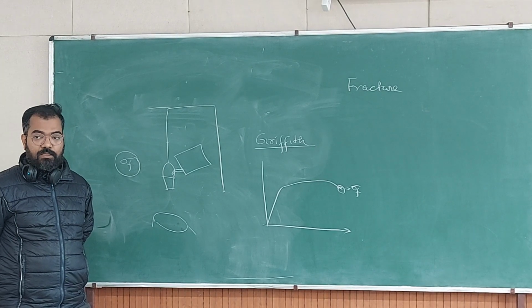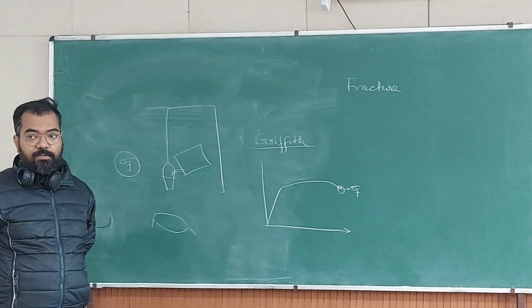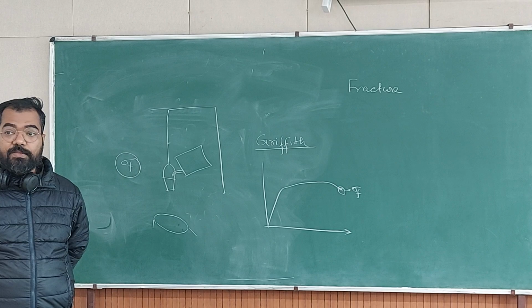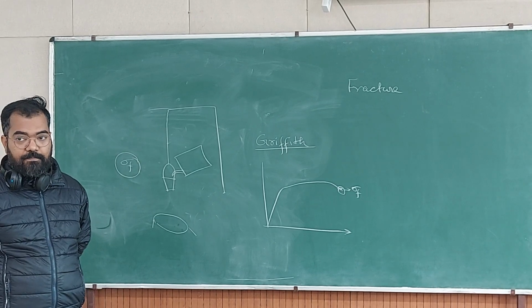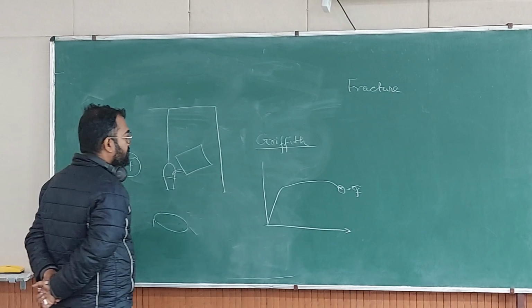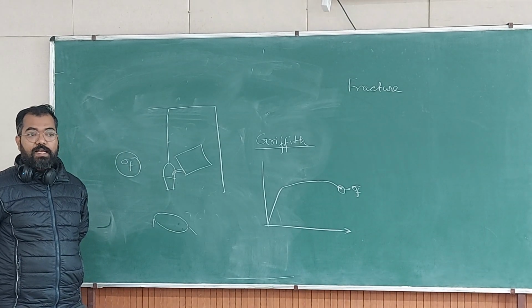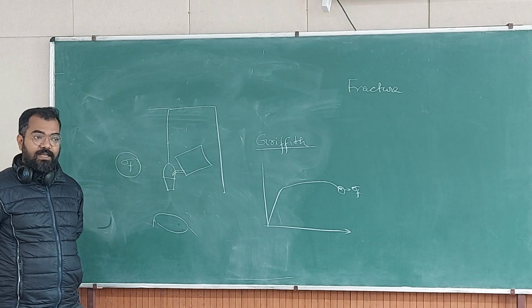No, brittle. Not completely brittle, but brittle fracture, because in those days the samples were made of iron, not steel. So it is cast iron. So the fracture is brittle, and the brittle fracture is dependent on the size. There is size effect in ductile fracture also.